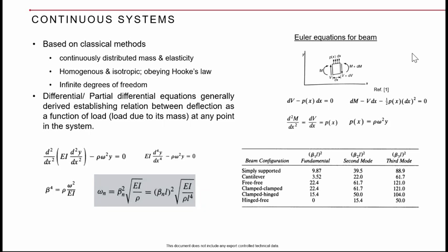Also, all the constants are derived, and you can go ahead and use Roark's formulas or from the textbooks, from Thomson itself, you will get this kind of equations, and you can get what is the first frequency, and you can find out what minimum unsupported length you can have between the bearings or between the brackets of a tube or a duct, so that your frequency can be maintained above certain frequency levels. So that is the significance of still using these basic principles of calculating natural frequencies.